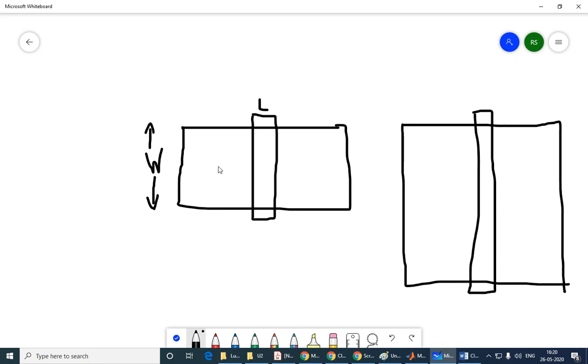So we have to remember where the current flows from. Current flows possibly in this direction. This is my I D S, the main current. There are other parasitic currents, we will not worry too much about that, but this is the main current flow in a MOS transistor, drain to source. So IDS flows from this side to this side. In this case also, IDS flows from this side to this side.